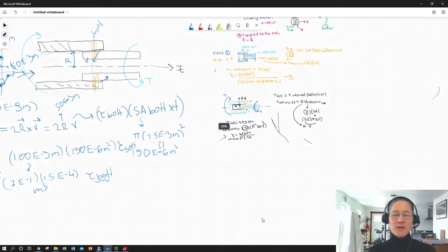So again, subject for later, but for now, V operating over an area, giving us a tau on the r face going in either direction, and then that backing out into equating to an applied normal load, P, or N, or to a torque. And we got a simple case in that all of that V is operating at the same radius. So from the point of view of the torque, it's a simple V r. And that is it for our tale of, well, I guess it was 2 loading, not 3 loading cases. But now hopefully you have a little bit better intuitive grasp on shear loading and shear stress.